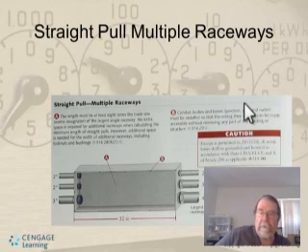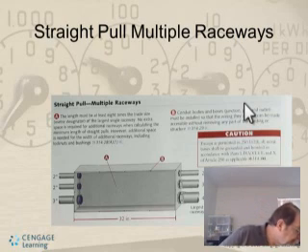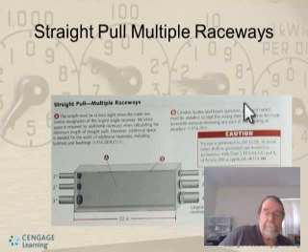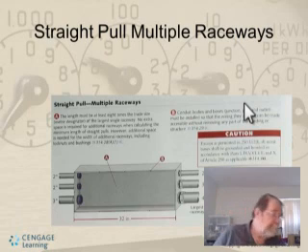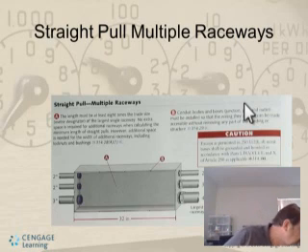So you usually pick the largest one, which is the bottom right, which is a 4-inch. Okay, so you take 4 times 8, which is 32 inches. So you have to have a 32-inch box, because you're figuring, then you also have to, well, I won't get into that. Your box calculations, you may need to know that.